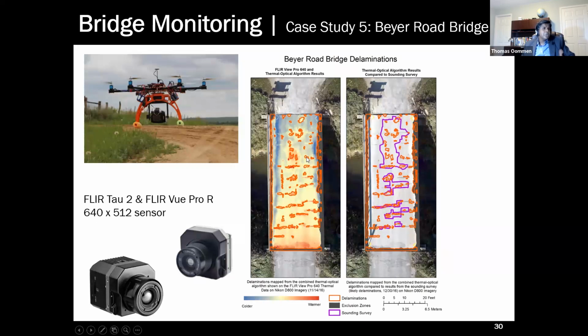So you can utilize this technology to monitor the concrete dams, the stability of the dams, how the concrete is performing. Traditionally, remote sensing techniques were limited to the surface, but we find that by utilizing some of these technologies like the thermal remote sensing, you can start to not only observe things at the surface, but also at the subsurface and look at defects that are going on.